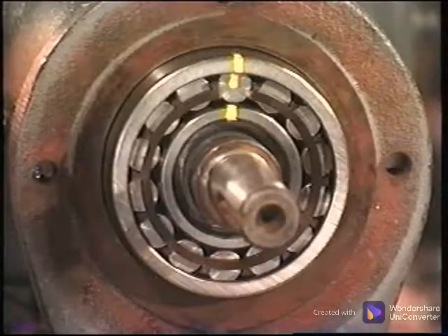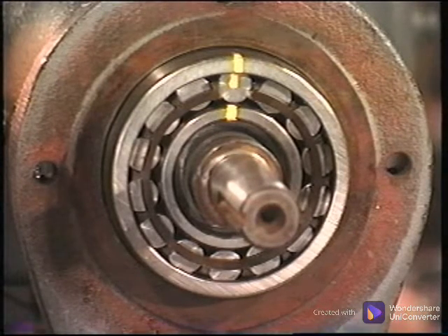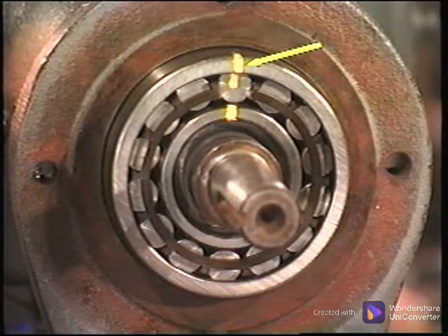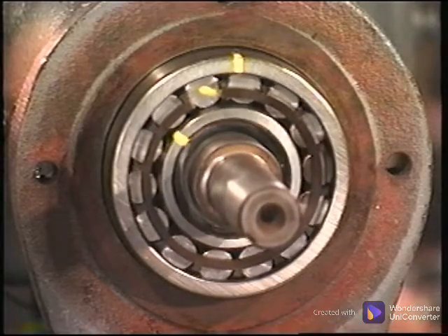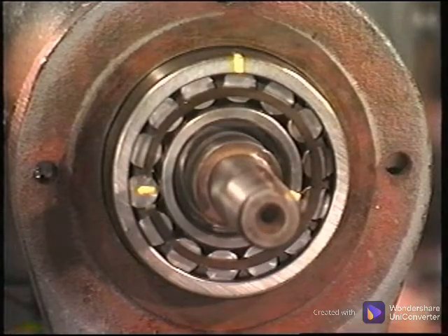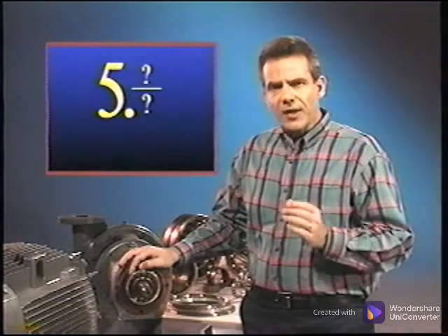That is, for each revolution of the shaft, how many impacts will be made due to a particular fault. This bearing has been marked so we can visually determine the approximate frequencies. If a defect is at this position on the outer race, we can count how many balls will impact the defect during one revolution of the shaft. 1, 2, 3, 4, 5, and just a little more. 5 and a fraction balls impact the outer race with one revolution of the shaft. Notice that it is not exactly 5, but 5 and a fraction.